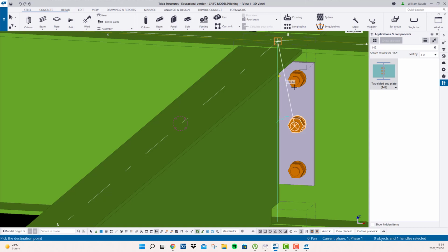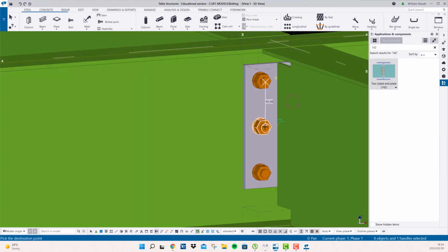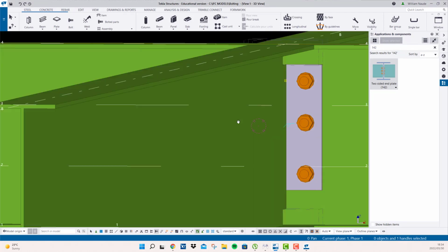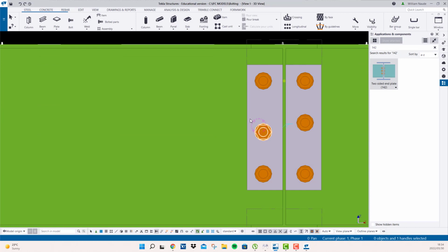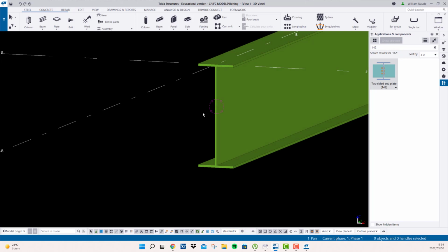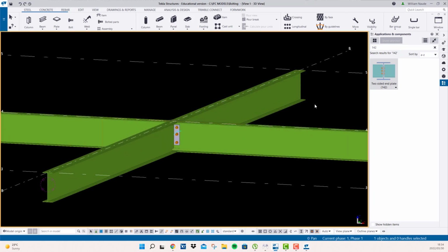You can choose this bolt, choose a point to point, say 10 millimeters up, and you can choose this one as 10 millimeters down because you want it maybe staggered or whatever. So this is how you can manipulate your bolting in spaces. So this is how you can choose a single bolt within your group of bolts. Right, so there we go. So there we have a quick idea of what bolting can do. Now, I'm going to come back.